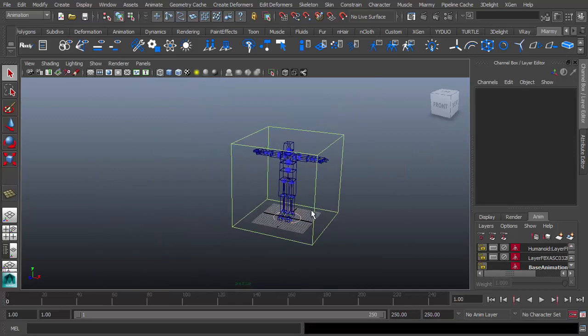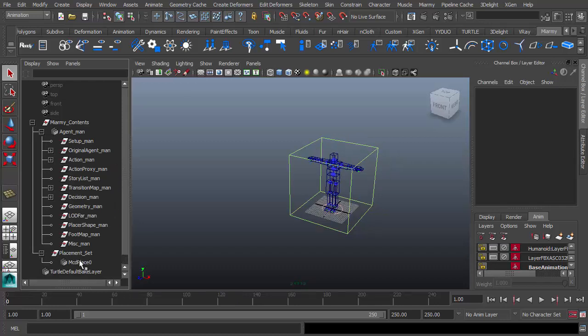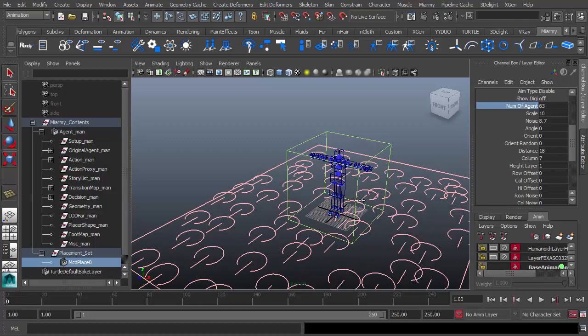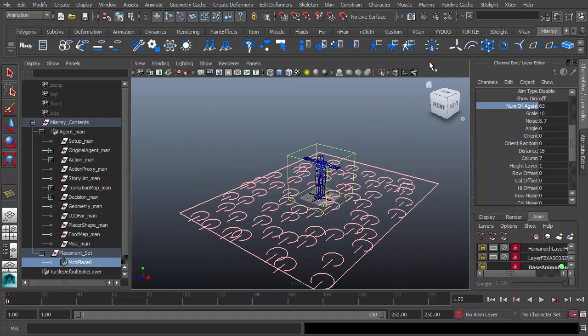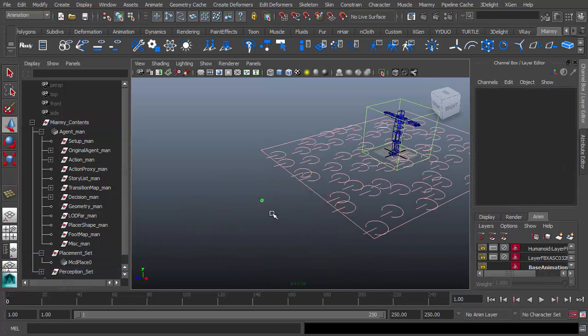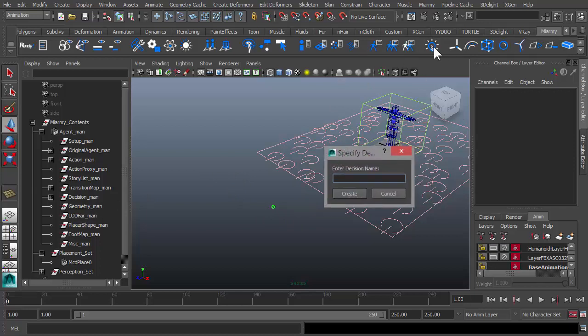From this file, let's first make the agent number bigger, select this place node, and increase the number, like this. And then let's create a spot. In the previous video we already introduced the spot usage, and you can make your agents interact with the spot by the distance and the direction. So let's just do that, and click the create decision here and the spot logic.